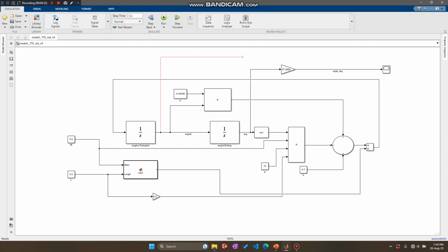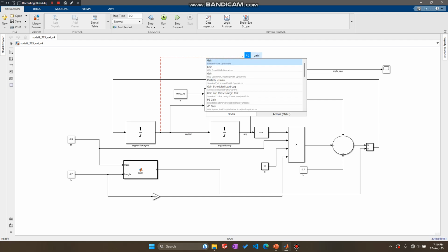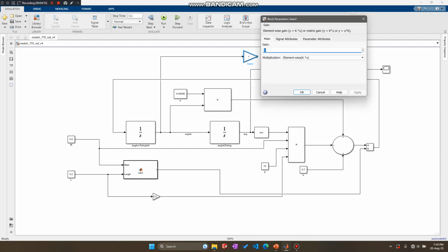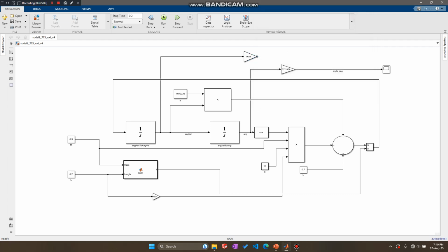So as one last demonstration, I'll show you how to plot angular velocity in RPMs. So what we have in this signal and any of its branches is angular velocity in radians per second. It needs to be multiplied by 9.54 in order to convert it into RPMs. Once again, if you do simple unit calculations, you can figure out these constants on your own, and I'll rename this signal as angular velocity in RPMs.